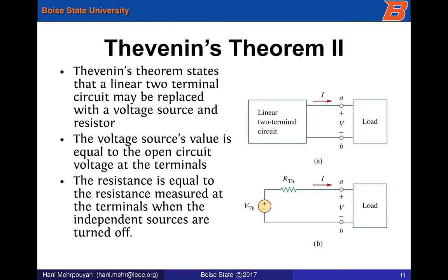So Thevenin's theorem says that what we could do is replace all the elements with a voltage source and a resistance in series with it. So all the constant elements can be replaced with a voltage source and a resistance in series with it. Now the voltage of the voltage source is the Thevenin voltage, and the resistance in series with it is the Thevenin resistance. So we have to determine those, right?